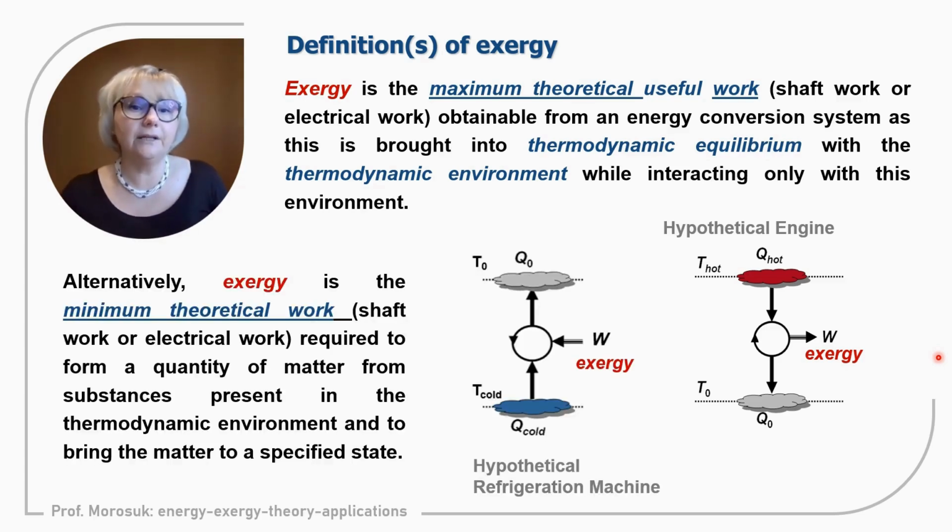And what is the alternative definition? Exergy is the minimum theoretical work that should be supplied in order to bring a system with conditions below the environment to the environmental conditions. So here, maximum work can be produced, minimum work should be supplied.